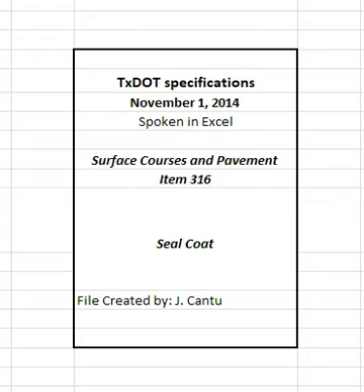Unless otherwise approved, match longitudinal joints with the lane lines. The engineer may require a string line if necessary to keep joints straight with no overlapping. Use sufficient pressure to flare the nozzles fully. Select an application temperature, as approved, in accordance with item 300, asphalts, oils, and emulsions. Uniformly apply the asphalt material at the rate directed, within 15 degrees Fahrenheit of the approved temperature, and not above the maximum allowable temperature.